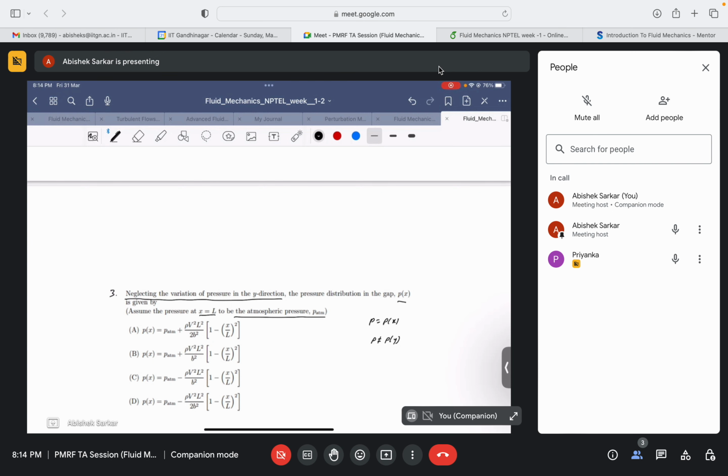Even if you take the unsteady form, because I also started initially with the unsteady form, you'll find that v is only a function of x. And since we're only considering along the x direction, the del v by del t term will already get cancelled out, right?